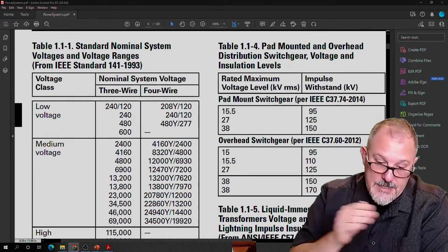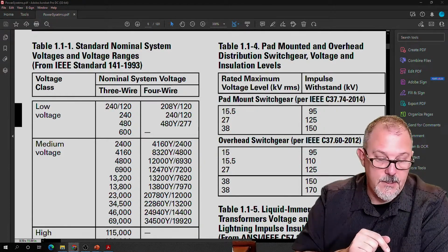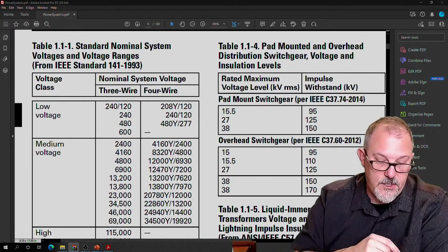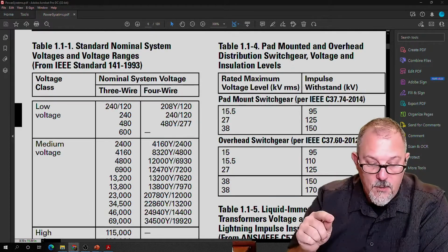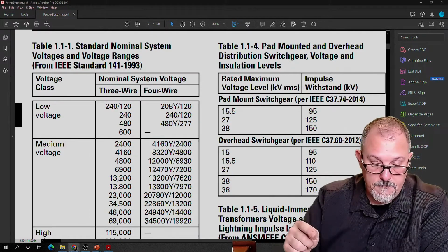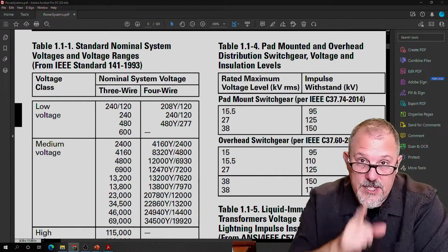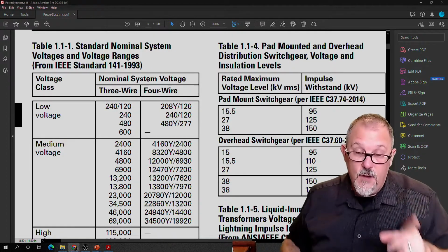And this is, again, a decrease of voltage by 10%. So you had 90% voltage. Your efficiencies will decrease. Your power factor will increase. Full load current will increase by 11%. Think about that. Full load current.